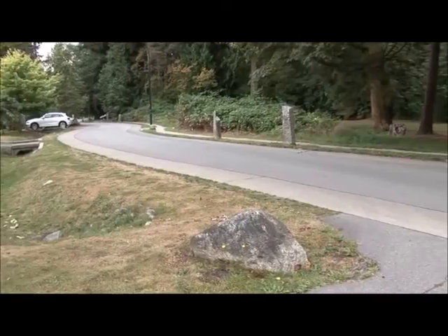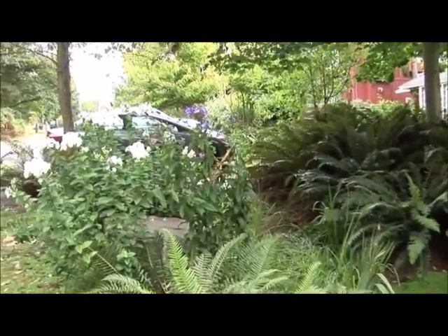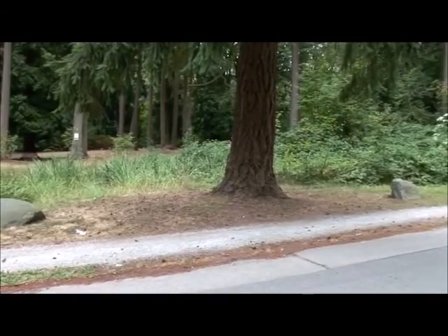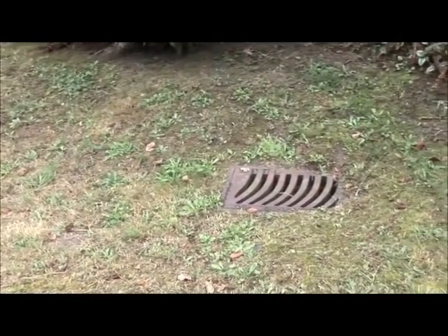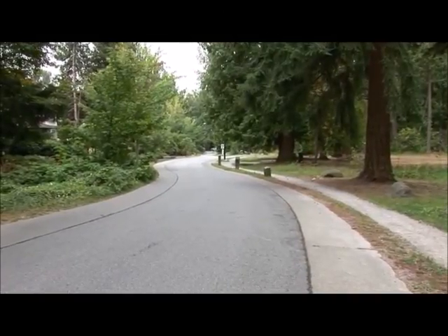Some of the swales are grassed, while others are planted and maintained as a part of homeowners' gardens. Some sections even drain into a wetland, indicated by the tall grass and rushes, while others have a storm drain for overflow. The road is purposefully curved to reduce traffic speed in this residential area.